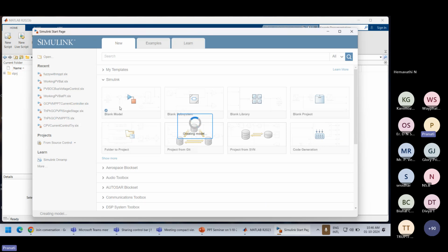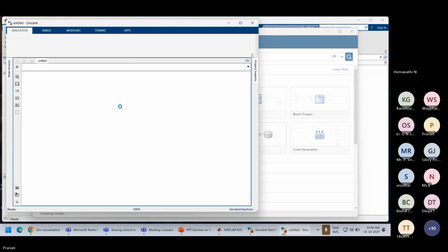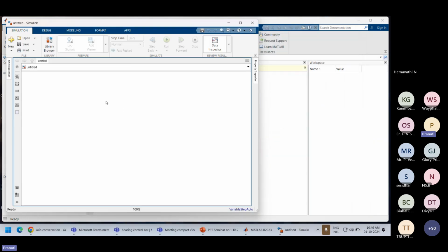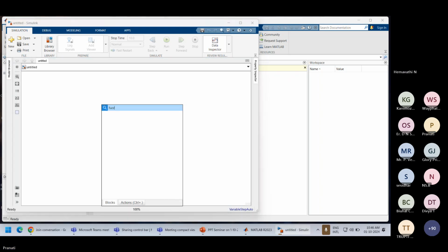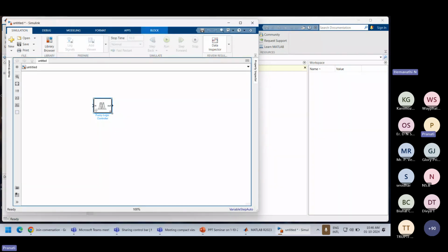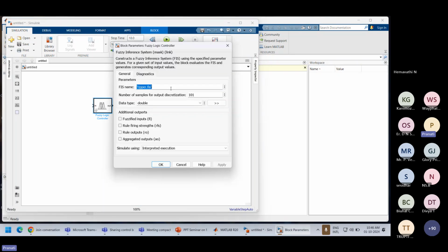You need to set the rules, that's all, and the membership functions. And it doesn't depend on the mathematical model, so it is very easy, not easy, rather it's an efficient method. The fuzzy logic control will directly give you this. You need to only put the name, whatever you have stored there in the dc.fis file. Whatever name you have stored there, this .fis file name should be the same, then it will work.